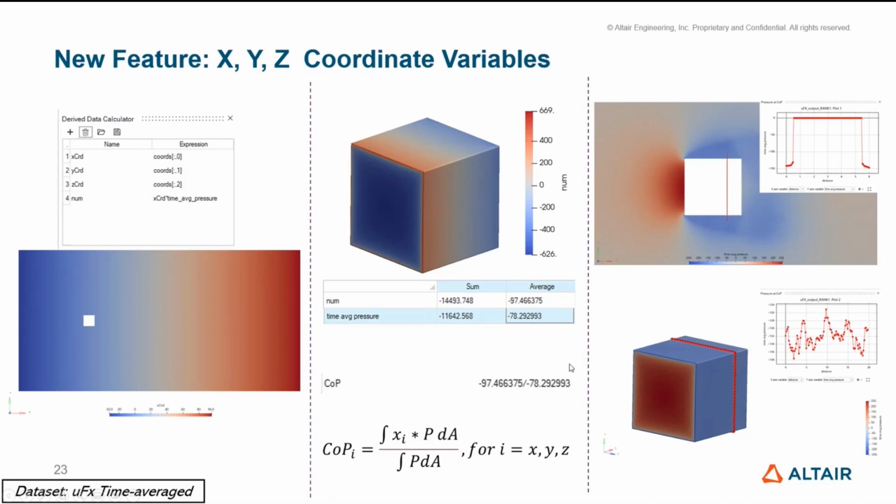So you see, this gives just a single value, and then I can look up via the intersection curve at that location. Okay, what is my pressure across a rake, for instance? And here I can see what's the time average pressure as I move from the recirculating part at the cube, but at the center of pressure. And then similarly, if I wanted to intersect the entire cube and then plot the circumference of that cube, or the perimeter of that cube, I can do that on a two-dimensional plot using the intersection curve tool.